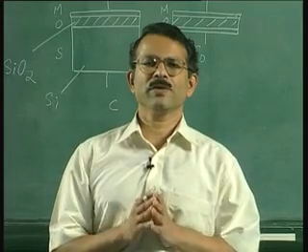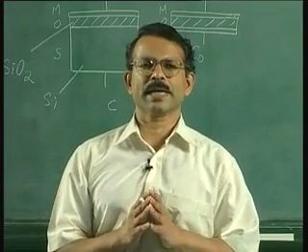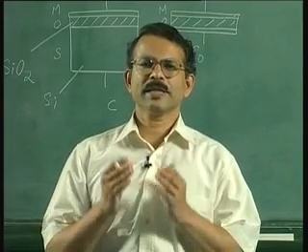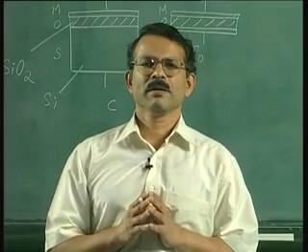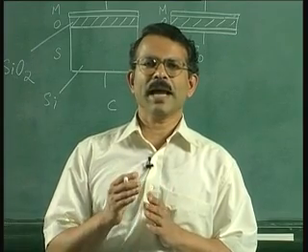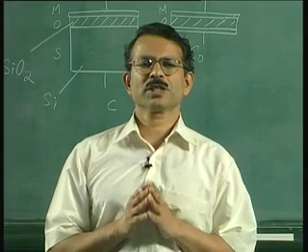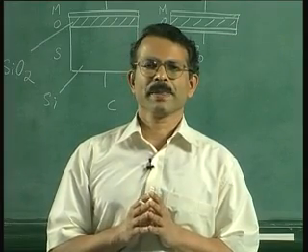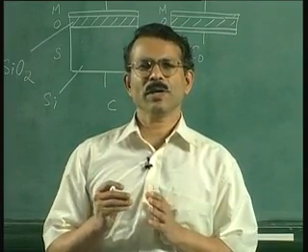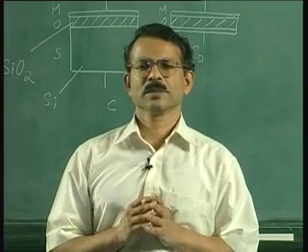For the capacitance, however, you do not have any DC current voltage characteristics because there is an oxide layer that insulates the metal from the semiconductor. When you apply a voltage to the structure, there is no DC current. However, when you apply an AC voltage, there is an AC current.